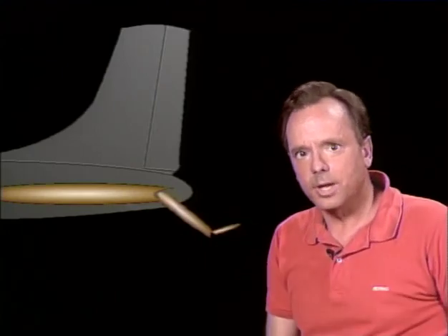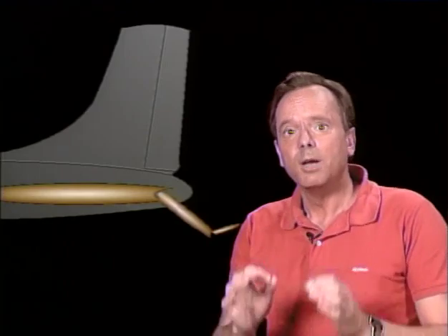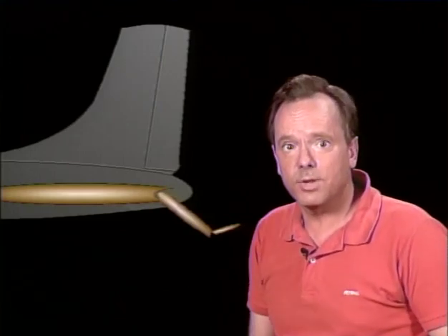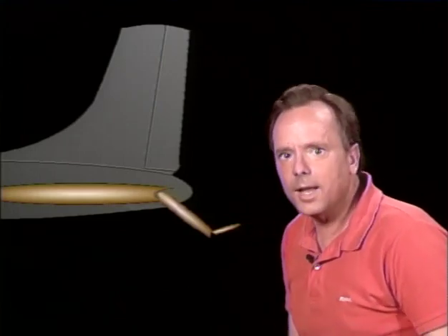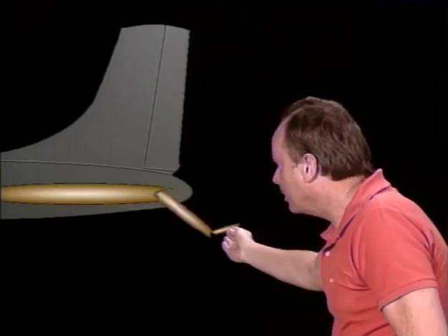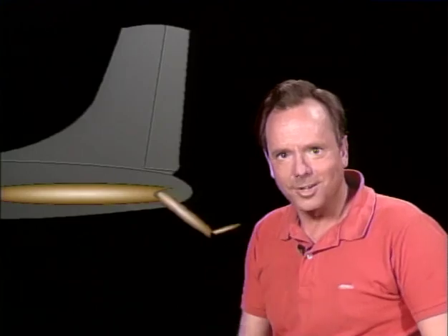So here's the question and the way it will read on the FAA written exam. Movement of the cockpit control towards the nose down position during an operational check of the elevator trim tab system will cause the trailing edge of the trim tab to move upward regardless of the elevator position. And that's what you need to know for the test.